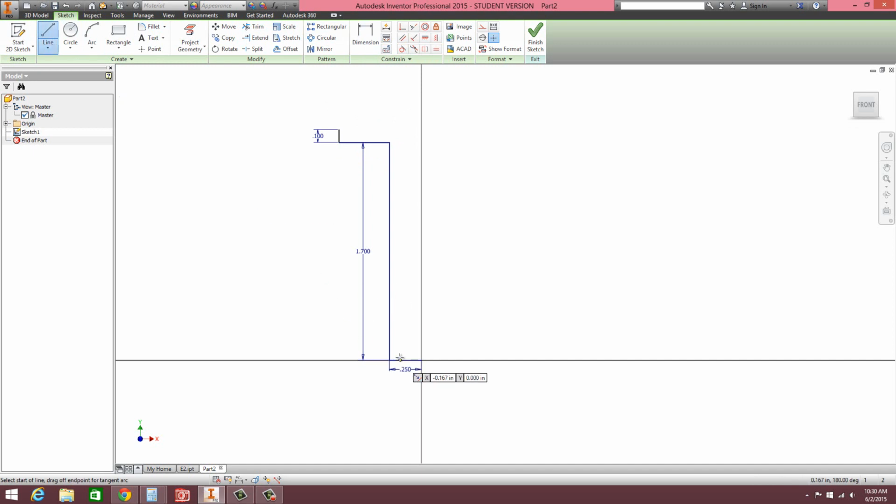Okay, oh actually click on line again, and we could close it off at the top here with a 2-inch line. And now we should be able to use the arc tool. In this case, let's go with 3-point. Could go with center point. 3-point's pretty, oops, missed the edge there. Sloppy sketches can really throw you off. Okay, in this case, it is supposed to be 0.75, so we could type it in, but you'll see there's a little bit of a discrepancy because it kind of bows out a little bit. That's because it's not centered off of that.